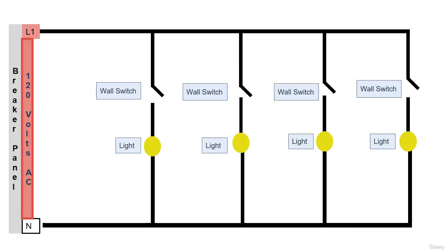A common parallel circuit you use daily is the lights in your house. Multiple lights will be connected to the same circuit. Series and parallel circuits are what we work with most of the time. Get used to separating the circuits mentally so you can troubleshoot. You will likely see multiple circuits within a circuit. Your ability to see them separately will help you troubleshoot more efficiently.